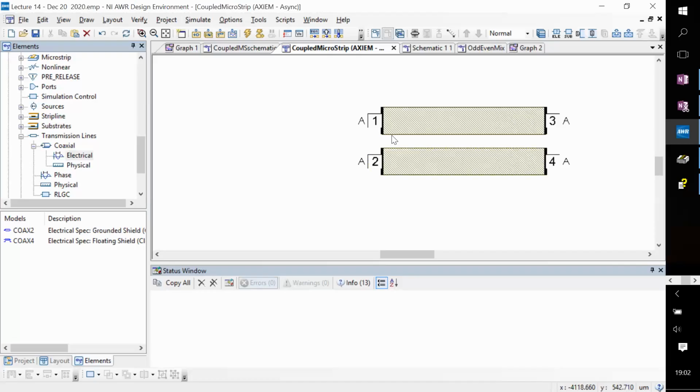But 1% of this power goes to 1. And on 1, you put your device, the one you're trying to measure. Okay. So that then goes to your device, reflects, and then 99% of that comes back out of this. So that way, the incident signal and the reflected signal have been separated.